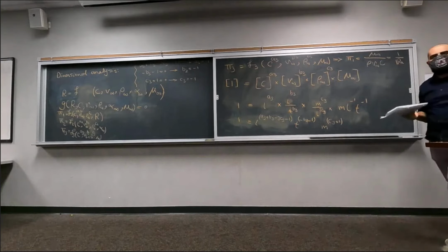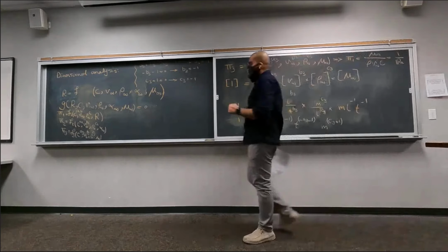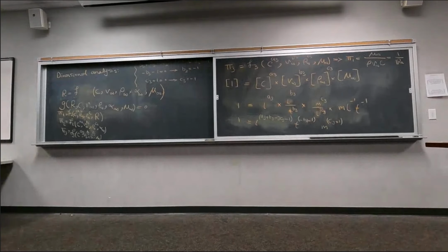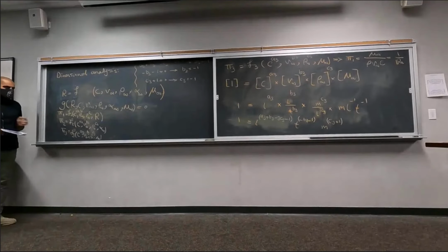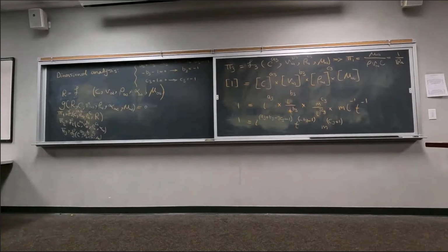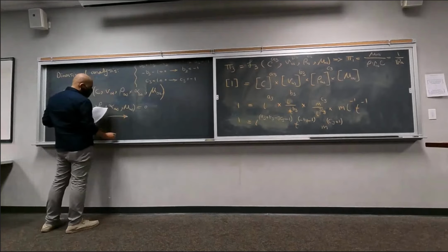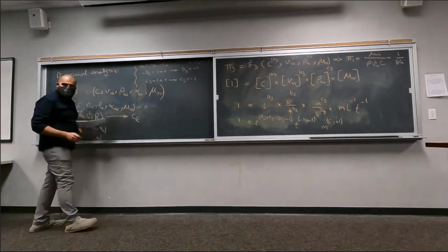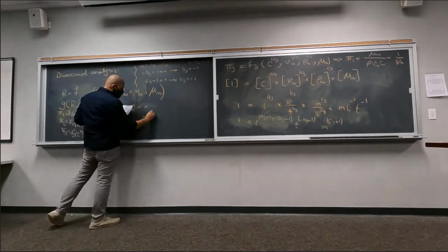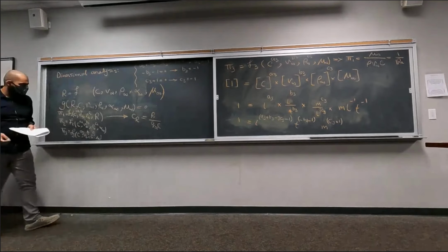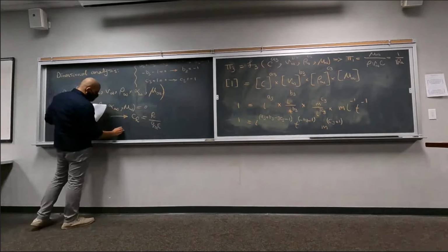So one of the dimensionless parameters that is going to help us in this analysis is going to be the Reynolds number. If you do this analysis for the rest of them, pi 2 and pi 1, you are going to find the force coefficient, CR, which we remember from the previous lecture, is R over Q infinity C, as well as the Mach number.